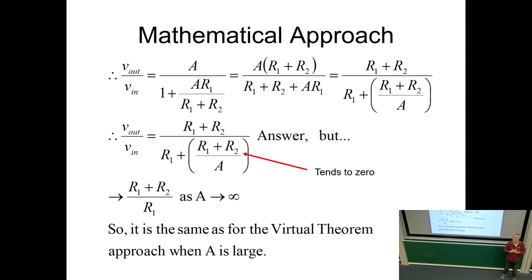If you want an amplifier with a gain of 10 to operate across the audio band from 50 hertz to 20 kilohertz or something, then it's entirely legitimate to assume that A is large across that band for your operation. If you went up to 100 kilohertz with that same circuit, A would not be large at 100 kilohertz. So the response of your amplifier would change with frequency.